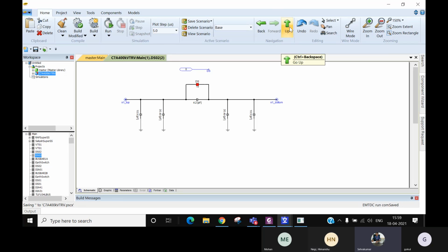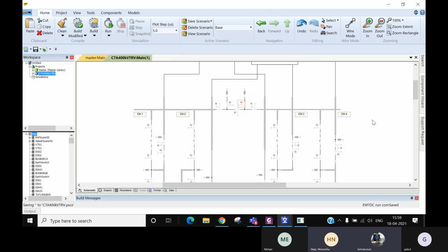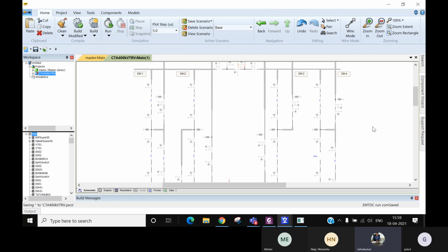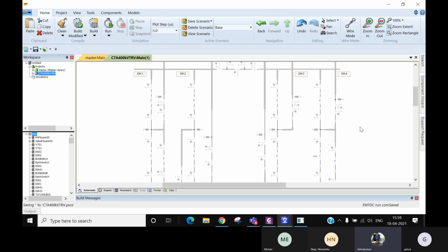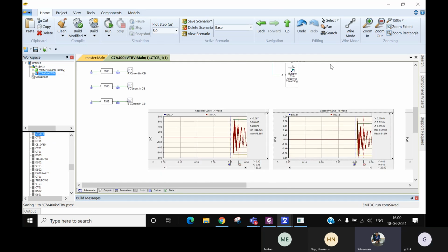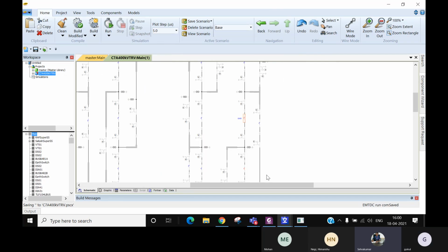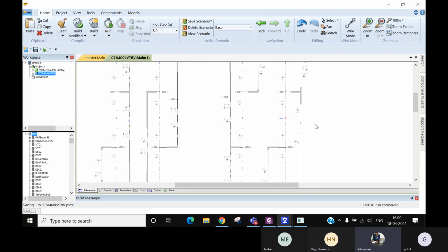So that probably means what is said has to be properly captured. That's the one key thing which we need to really look into. Yes. Then the second, more interesting point which we need to really look at is this TRV is not a static parameter like what is stated in the standard. Correct? The dielectric strength of the breaker will increase when the contacts start separating.